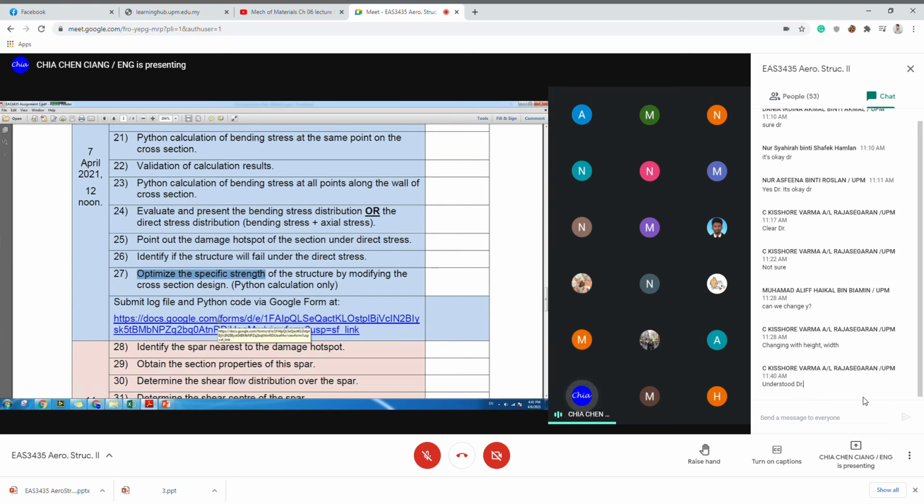When you reduce the amount of thickness, for example, reduce the amount of material until a point where the bending failure will almost occur, then it is an optimum point. So the second direction is from no failure at all, not possible to have failure, you optimize it so that it nearly fails.